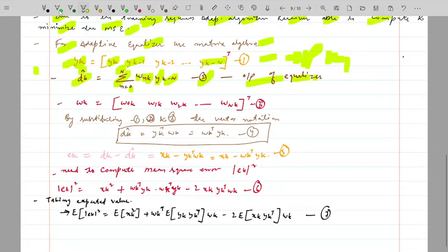Now for the third equation, this is the equation for the weights of this equalizer, or we can say the multipliers of this equalizer. So w of k is also a row vector here: w0 of k, or w naught of k, for this y of k; y of k minus 1 for w1 of k; y of k minus 2 for w2 of k; and up to y of k minus n for wn of k, transpose.